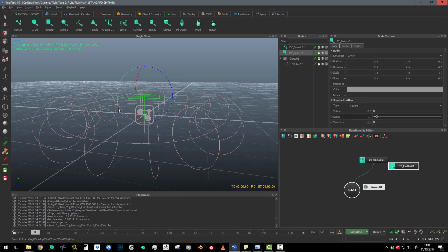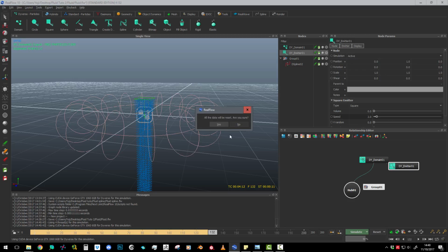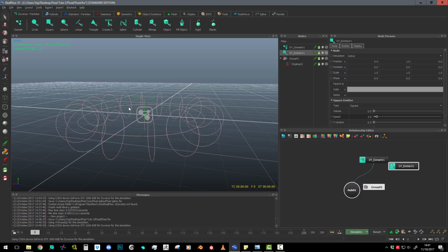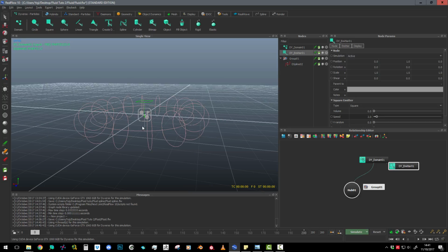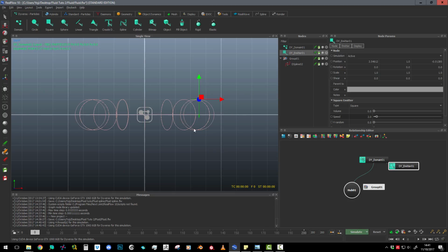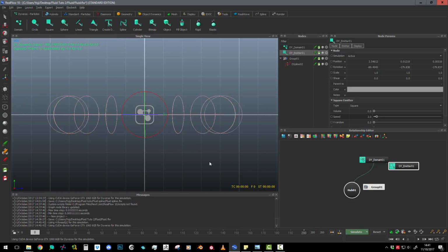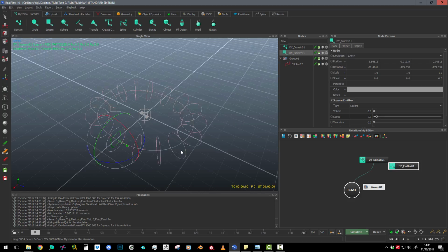Okay. And as you can see now, if I start to simulate here, I will have some particles go down, in the perpendicular axis of the plane. To reset the simulation, I do yes, like this, reset. And I would like to put it inside with a good direction. So I will go in top view and move it with this tool to the side like this, and in side view I will use this like that, and make a little rotation on it to put a good direction. And so now if I put a good view, you can see that it's inside.